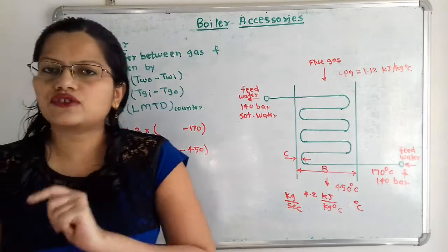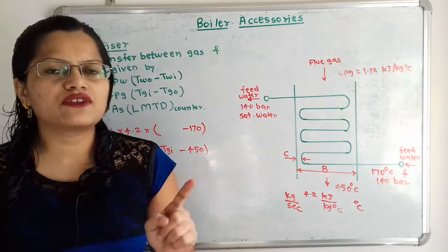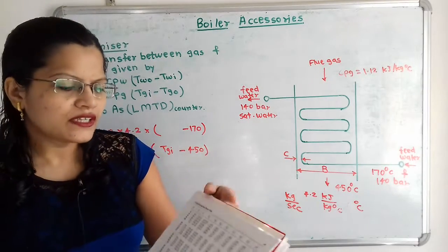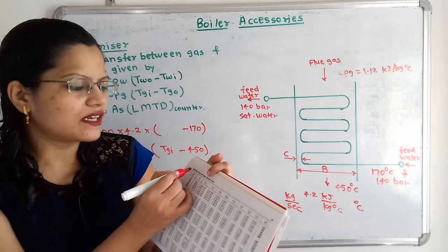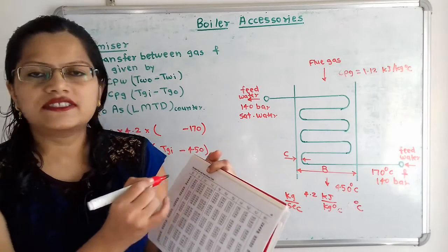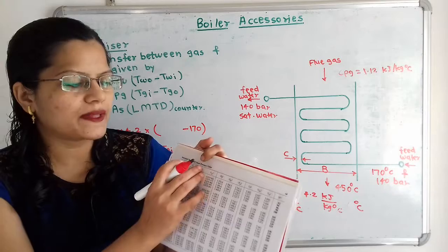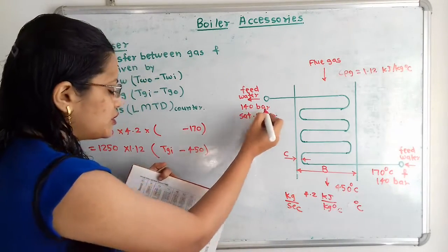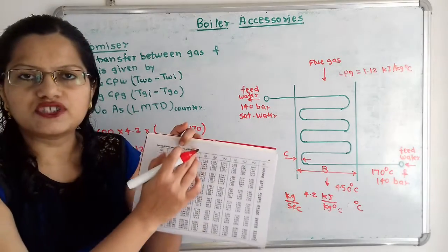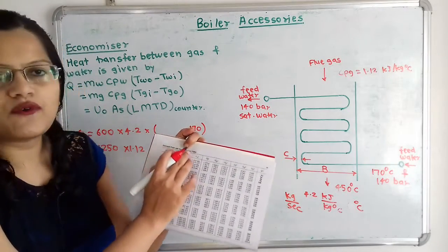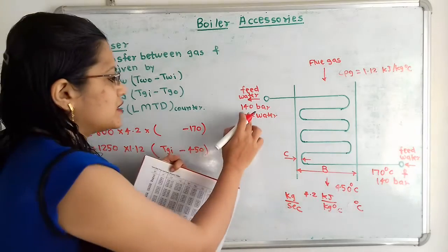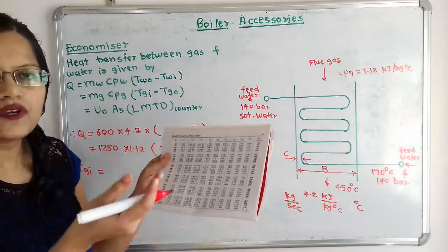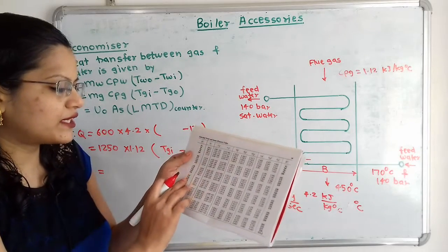Whenever saturated water is given, we can use the steam table. In the steam table the heading is saturated water and steam pressure table, with pressure table in brackets, because we are referring to pressure, so we refer to the pressure table for saturated water and steam. The condition is saturated water with pressure given, so we will find the temperature for 140 bar.